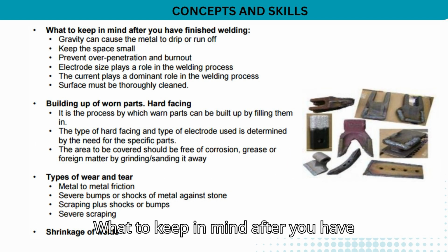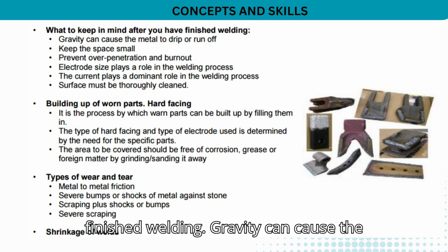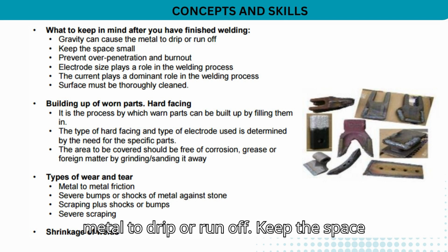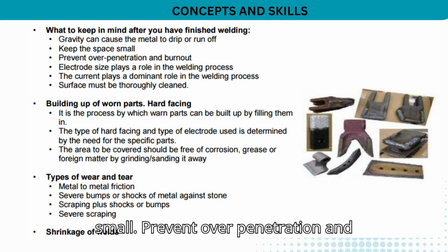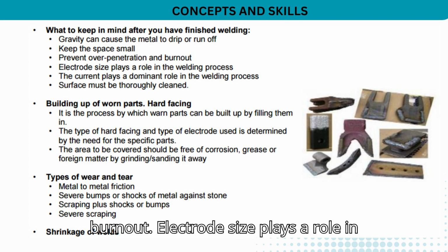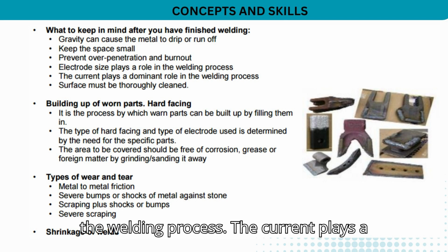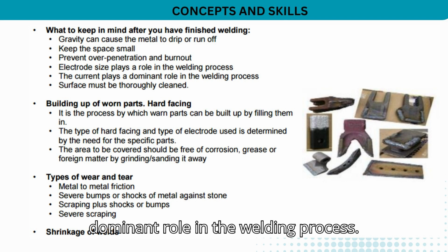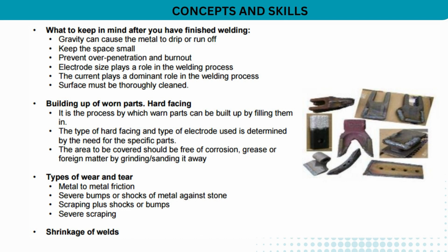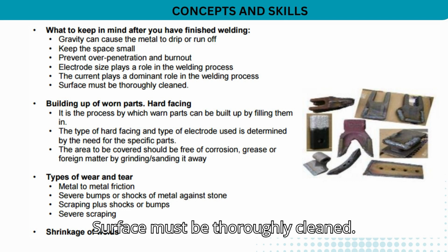What to keep in mind after you have finished welding. Gravity can cause the metal to drop or run off. Keep the space small. Prevent overpenetration and burnout. Electrode size plays a role in the welding process. The current plays a dominant role in the welding process. The surface must be thoroughly cleaned.